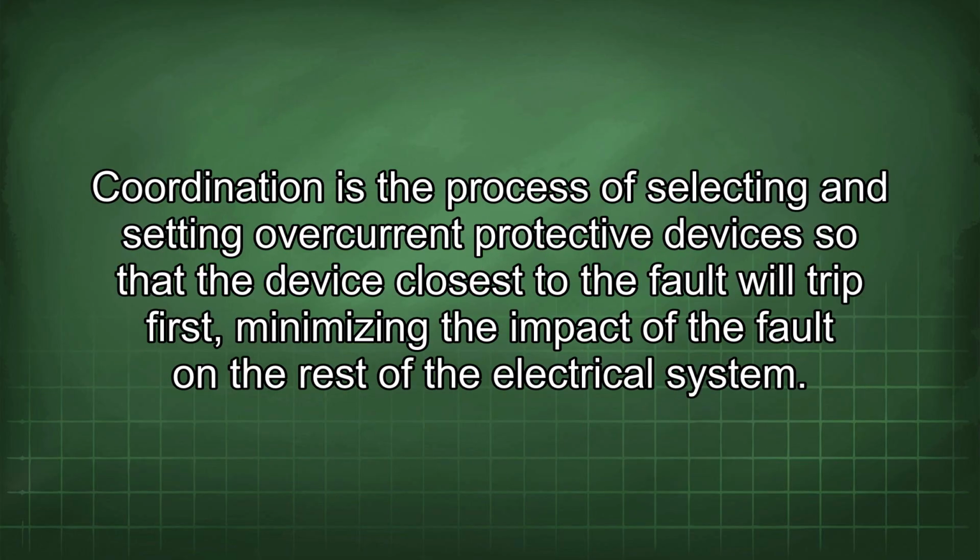Coordination is the process of selecting and setting overcurrent protective devices so that the device closest to the fault will trip first, minimizing the impact of the fault on the rest of the electrical system.